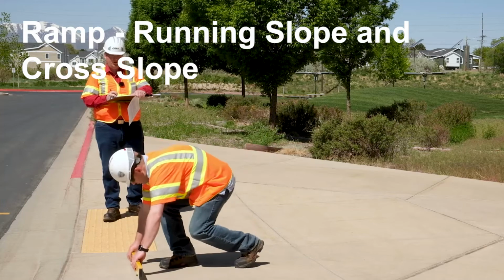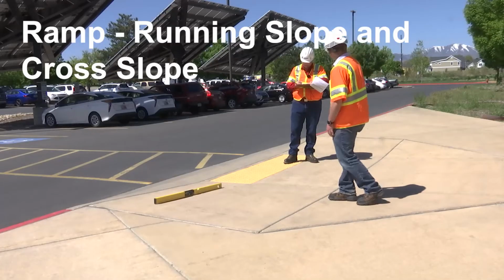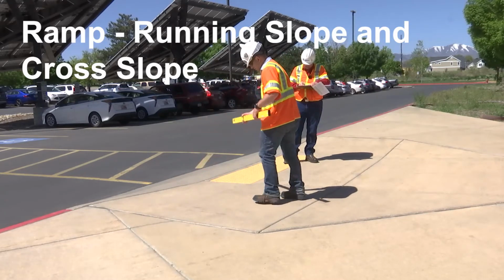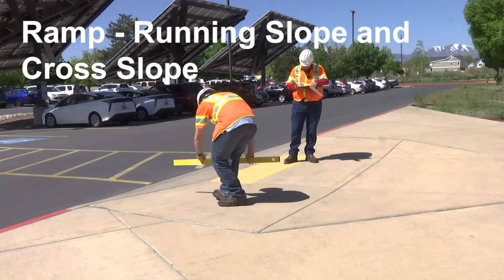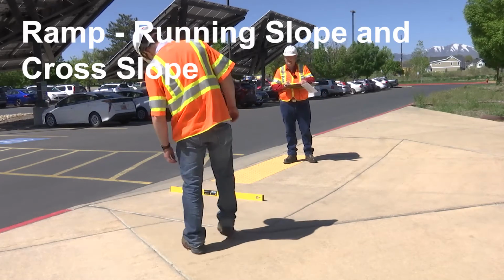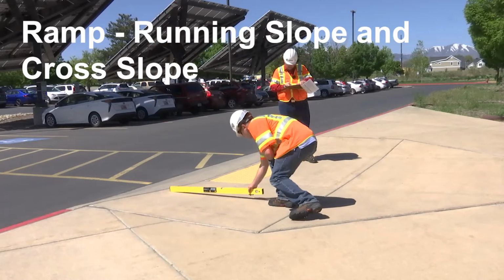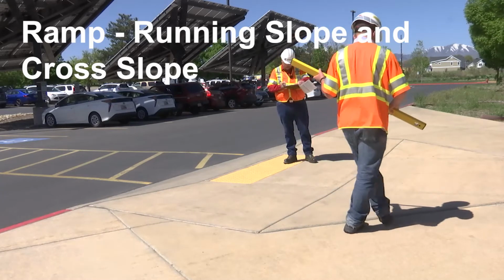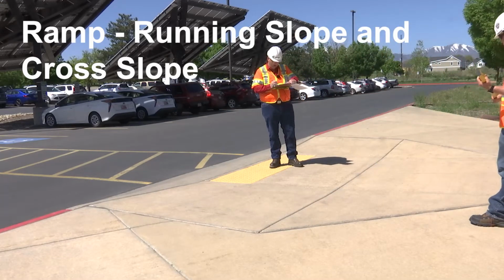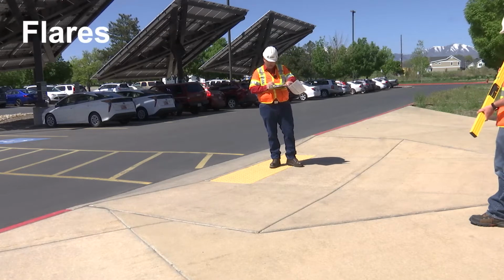And for the right, we have a running slope of 7.2% and a cross slope of 0.1%. So all of our running slopes are less than 8.3%, and all of our cross slopes are less than 2%, so we pass. Next, we move on to flares.